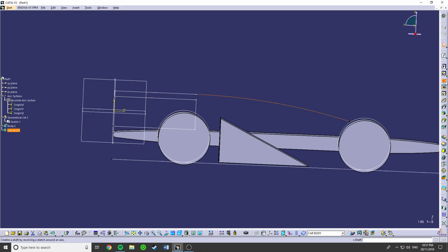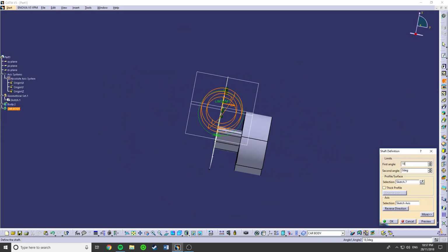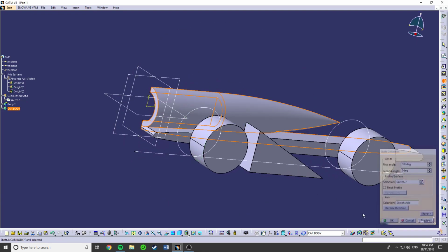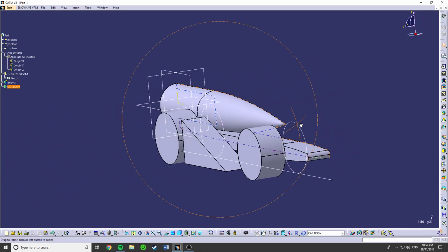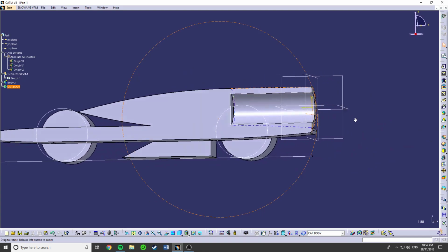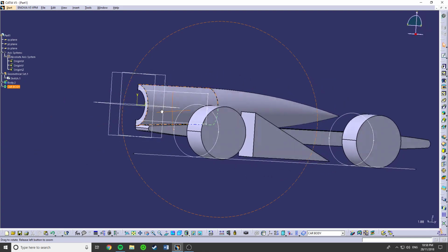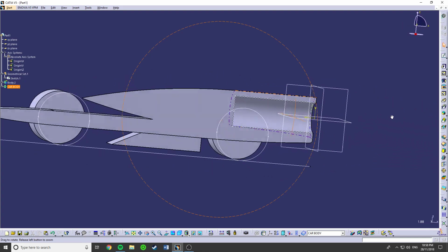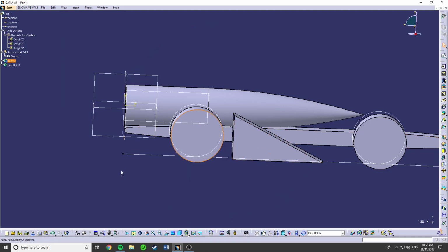Now that we've got this sketch selected, we'll shaft it. We're going to choose 180, and we'll click preview, and that shows that side. So this will kind of place it in there. You've got your hole already in the chamber, and this is a simpler way of doing it than the other way. It's a bit easier, it's fewer steps, and it produces a really nice result.